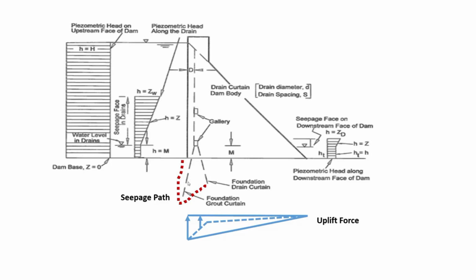Dams have to store water, which is the main purpose. These dams are founded on different rocks. Some are very good and some are poor rocks. Concrete dams are generally placed on good rock. However, still there is a chance of seepage below the foundation. This seepage causes uplift pressure. Seepage depletes reservoir and also may cause erosion or piping problems.